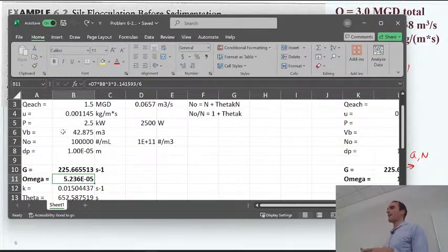So it makes sense that maybe 1/10,000th of your bottle of water is volume that is particles, right? If you have a complete slurry, then you still have a lot of volume of water there, but there's a fair amount of particles, so maybe that gets closer to 1. If your volume is all particle, then that should become 1, and you should never have higher than 1. So you can double check your flock volume. It should be a pretty small number.